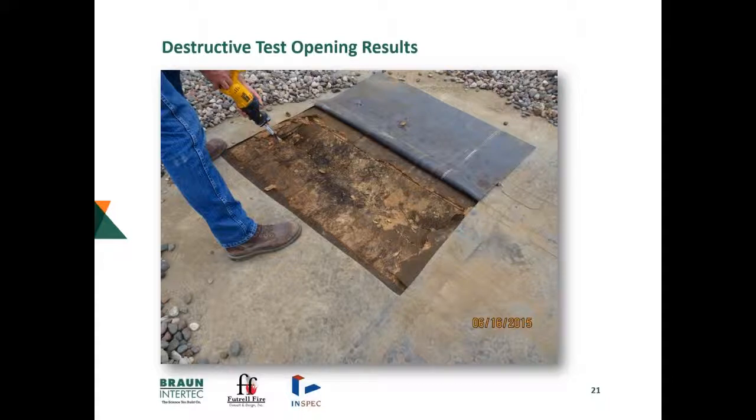As you can see in the upper side of that test cut, there's a fracture line. That's of the cover board that's deflected down, caused by the deck that's deflecting and fracturing below that. So when this gentleman stepped in this area, not this guy cutting it, but one of the operators on the roof doing some maintenance work, he felt this compression, and that's what we opened up.